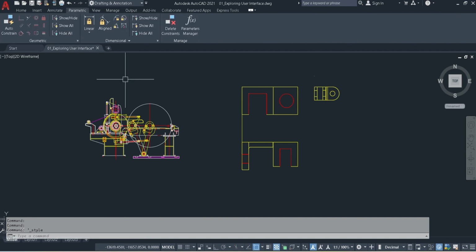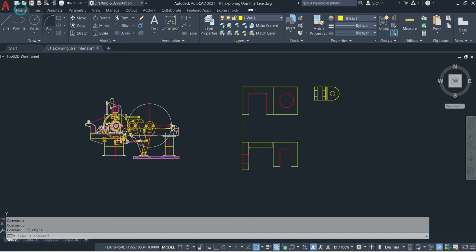Now the good thing about this is I can go into them there. Let's go back to the Home tab on the ribbon now, and what I might do is click on the Line command. That immediately kicks in the Line command, and you can see there in the drawing area when I move the crosshair in, it's asking me to specify the first point of the line. I'll just hit ESC there to cancel that command. That's what you do. You go to the panel on the ribbon that is on the tab, and you can find the icon that you need. You click on it and then you start working in AutoCAD.